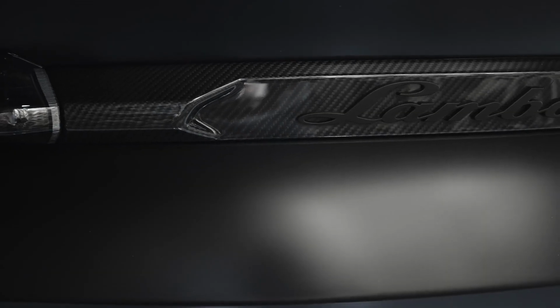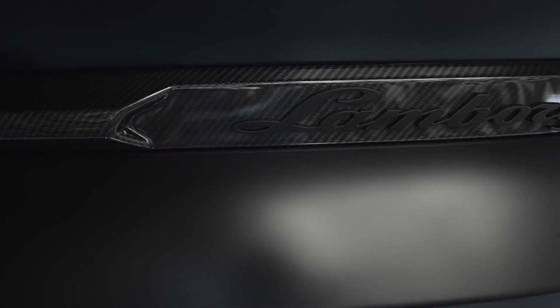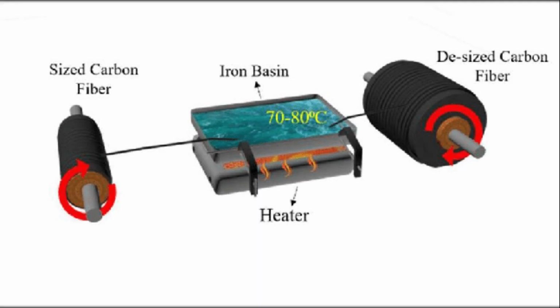Although these changes occur on a very small scale, they have a huge impact on the performance of the final material. The modified surface allows resins to adhere much more strongly to the fiber, creating a durable bond between the two materials. After surface treatment, the fibers receive a thin protective coating known as sizing. Sizing is typically a very thin polymer layer applied to the fibers. This coating serves several important purposes.